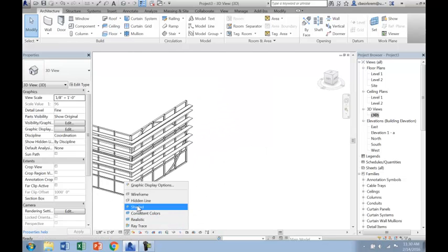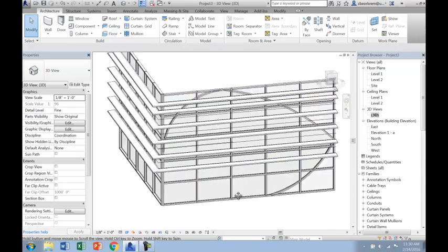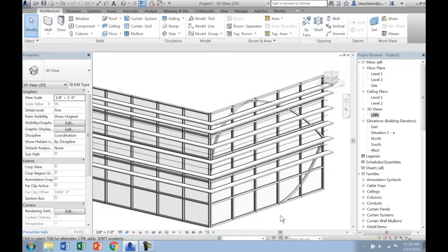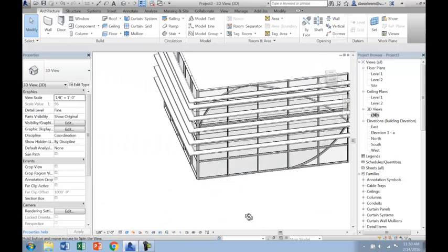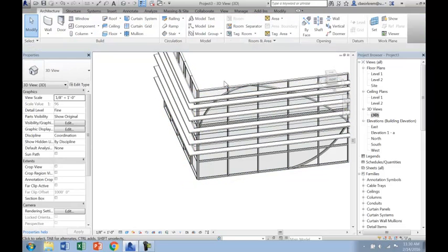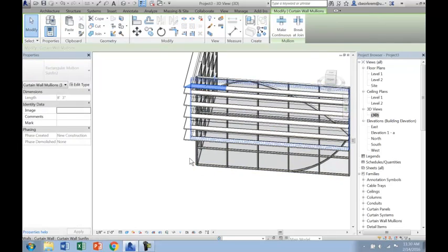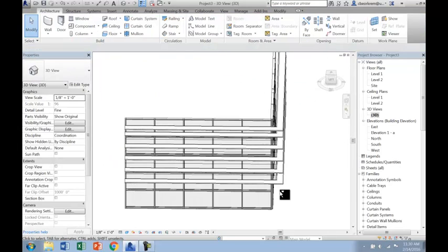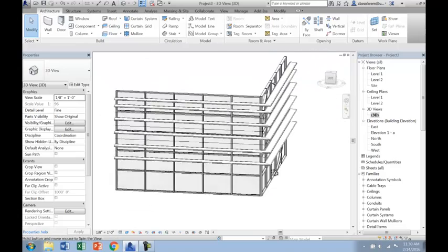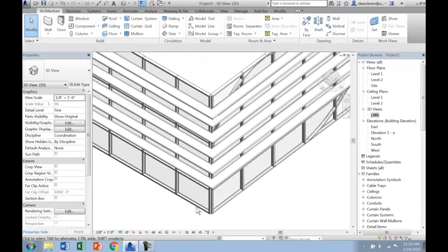If we look at this in the shaded view, now you can see I've applied this kind of shade system to two different wall systems, right? So I've got one that's the traditional mullion, the vapor barrier, and thermal barrier for my building type, and then I've applied another one to the face. I'm still missing the kind of horizontal mullions that I might use to hold this thing up. So we still need to come back in here and edit this wall type to add in some structure.